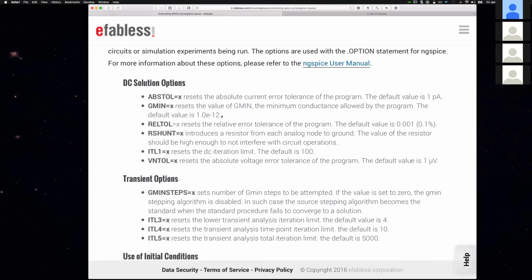So you always have to understand the ratio between such a Gmin factor and the impedances of the nodes you're looking at. Making it too high, you're basically putting a filter on what the simulator can see. My recommendation in all these cases is to run multiple values and understand the sensitivity of the circuit to the specific parameter.